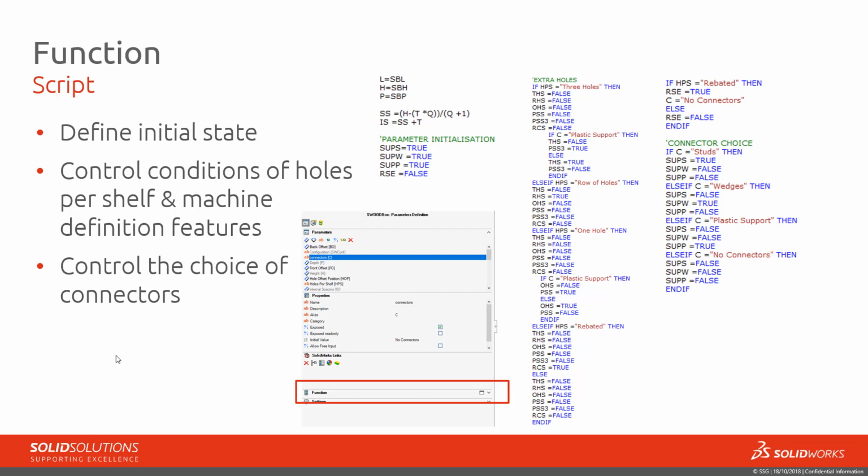Beyond that, you've got if statements, which are ultimately controlling the visibility of all of those variables as it goes through its various options. Now having this code in play will allow the end user to define how the SWOOD box ultimately appears when moving this into a SWOOD frame.